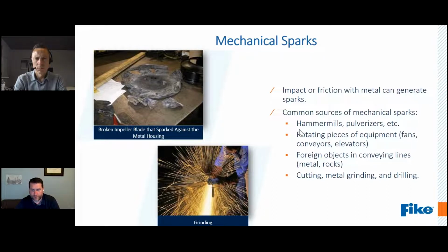You can have rotating pieces of equipment like the fans and conveyors, blower packages, any of those air moving devices. If that rotating equipment gets out of alignment and is damaged or hitting the housing, it can create sparks.